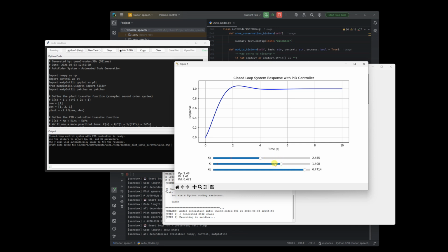And these are opposites of one another, integral and derivative. I can put more integral in, but you see you get more overshoot. As I turn down the integral, I get this offset, but it's highly damped, but I get a huge offset, so it's no good without integral. Just about every control system needs integral, unless there are some exceptions. If you maybe have a heating controller or something, you don't really need integration because it doesn't matter if there's an offset by a tiny amount. For very high precision you would, of course.